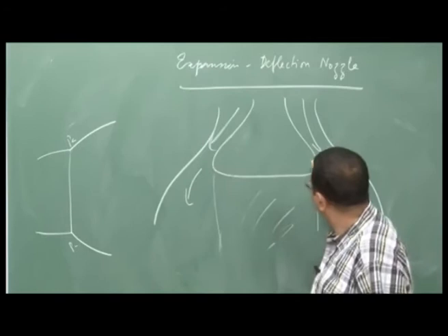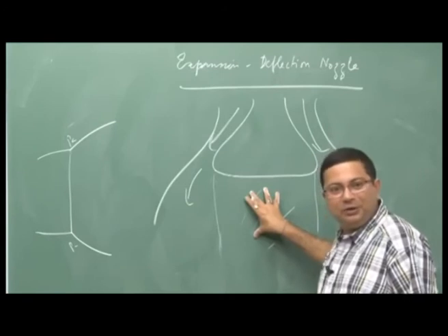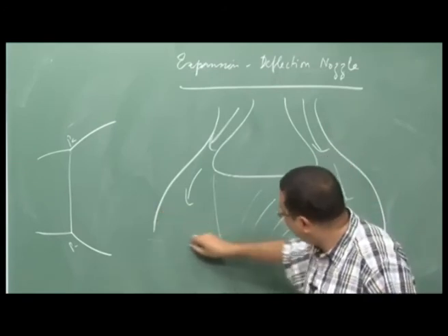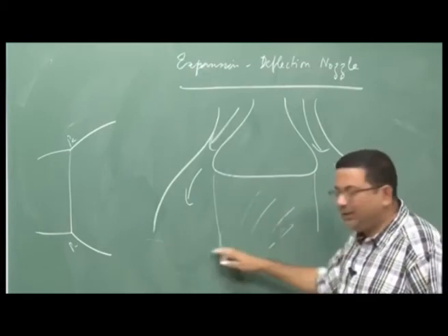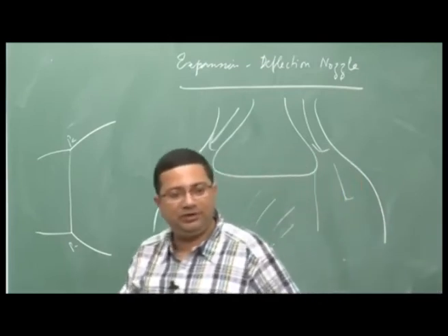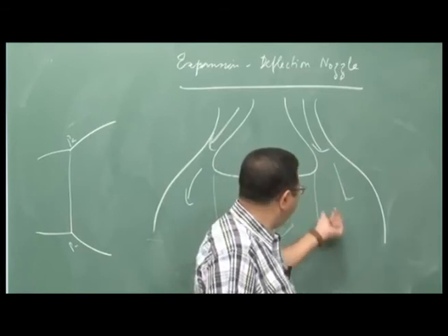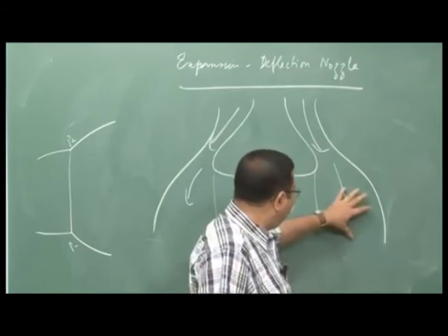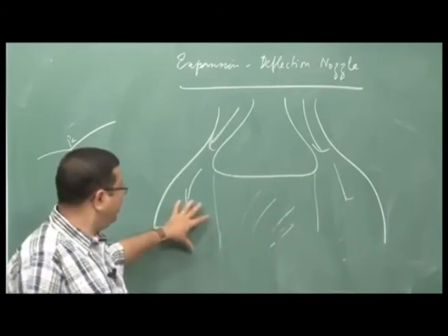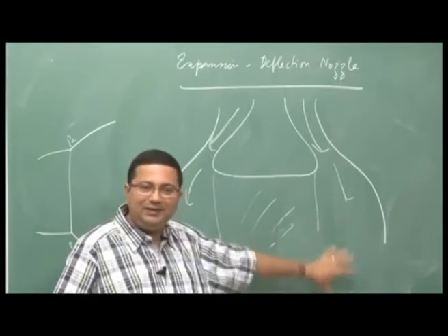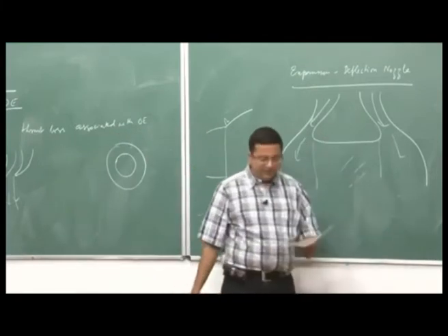So, now depending on this location, we create the shock wave or whatever it is required, and this is the ambient. So, by that time it comes to the end here, all the bad phenomena occurs here, and finally, when it comes to the exit, it has almost matched the ambient pressure. So, all the shock formation, all the expansion waves, everything will be occurring here, because this is my jet boundary. Okay. And then therefore, all the effects are confined inside, but not directly affecting the flow field. This is safe. What is happening is in this passage. So, this is called expansion deflection.